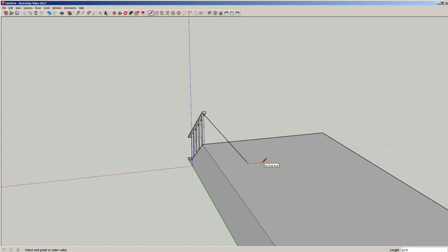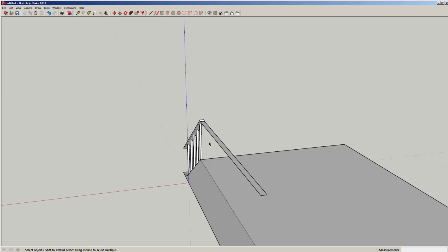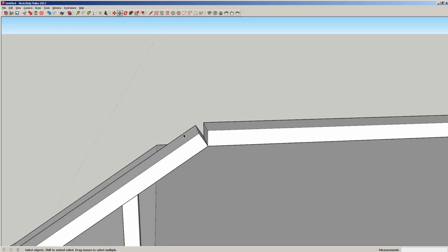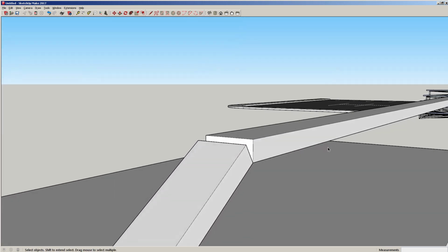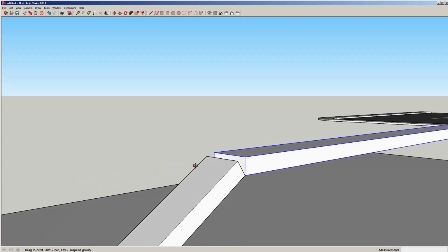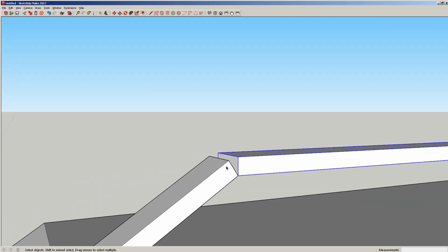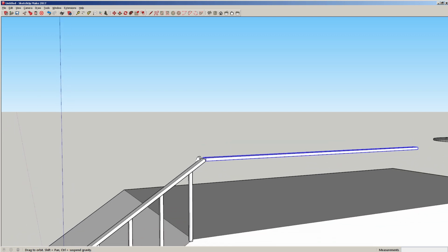Let's see here, I think we went 0.25. Alright, there's our face. I'm pretty sure we pulled it up 0.1. Yep, looks good. Now yes, we have a little gap here. This is difficult to fix. So for simplicity, let's just leave it, because you get the idea. But you can rotate this edge and rotate this edge and make them meet in the middle. Usually what I do is draw a line. So you find the center and they'll meet in the middle and they'll connect just fine.